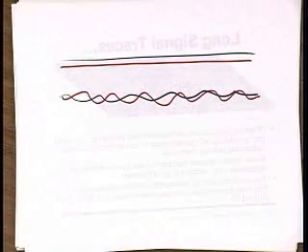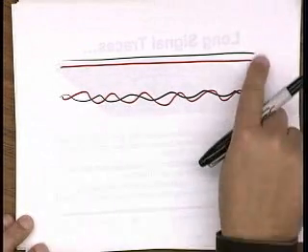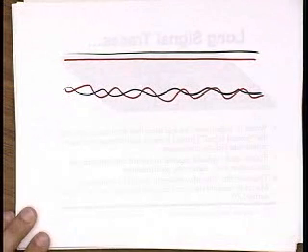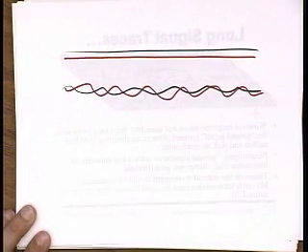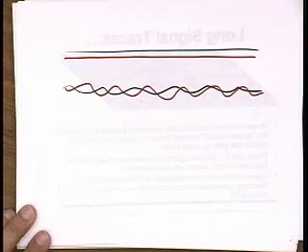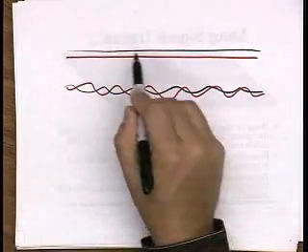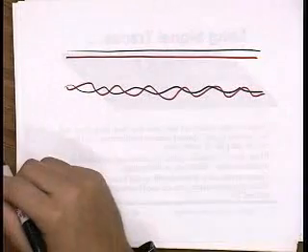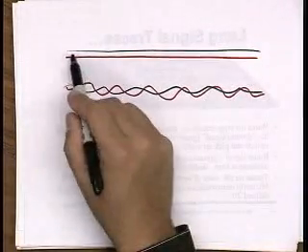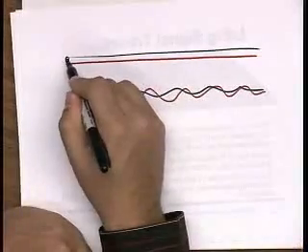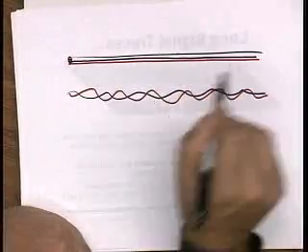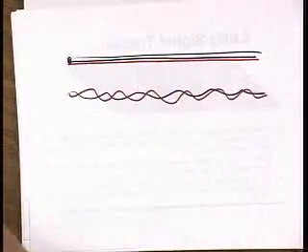Okay. So why is it that when you cut your phone wire and look inside, it's like this, not like this? Okay, Christian? If you twist them together, you keep them as close as possible, which is 2 radii away. Okay, that's one reason. But let's say I just stick these together. I can make these wires basically physically touch each other. And then I have the same spacing.